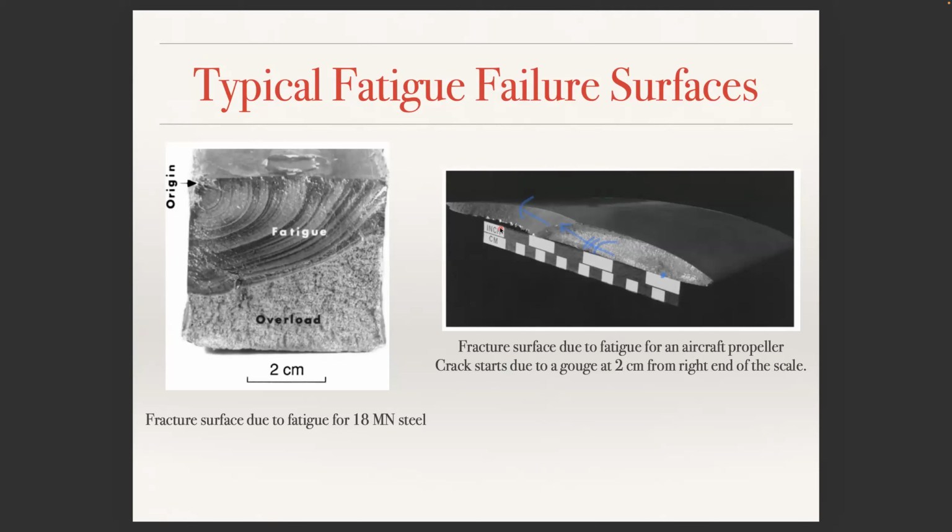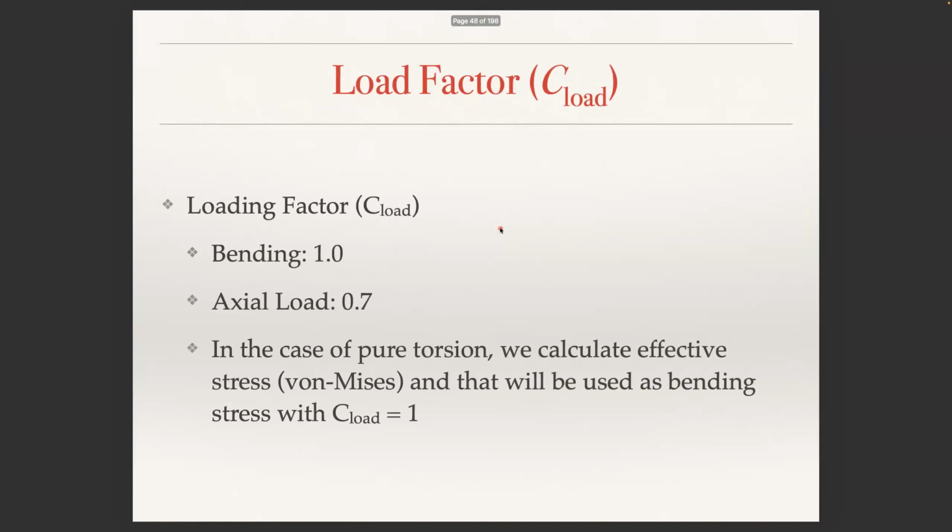In the case of static loading, we are only looking at the plastic deformation followed by fracture, but there is no repetition of cycles. And even in static tensile loading, we are interested in the yield strength of the material, which does not change significantly because there are no other effects that we will see in the case of fatigue. Okay, we will see why it will not be possible to use the same conditions.